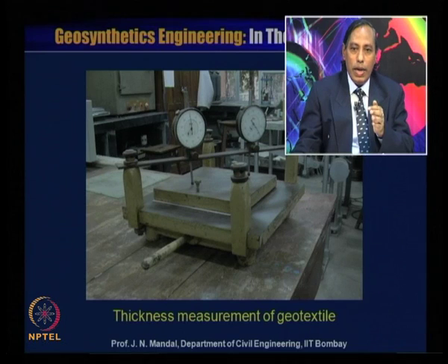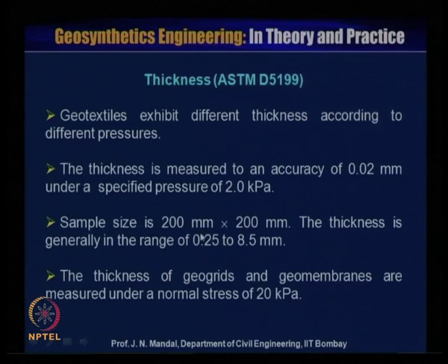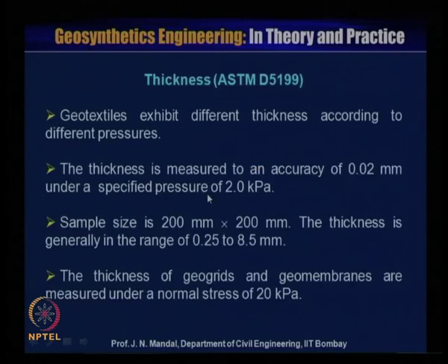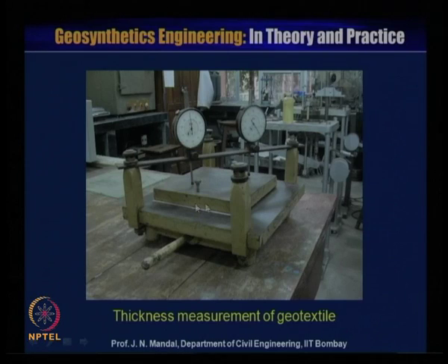You can see here the thickness measurement of a geotextile. You have to place the geotextile material here, whose size is 200 millimeter by 200 millimeter, under a specified pressure of 2 kilopascal.